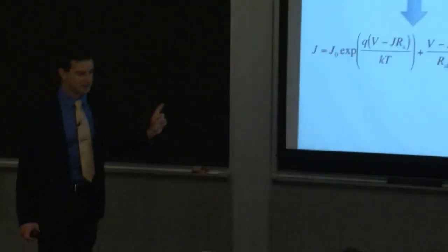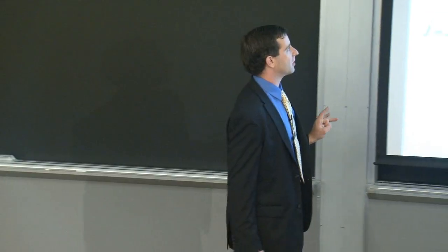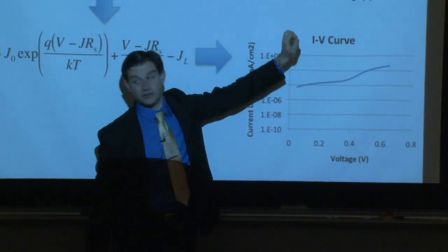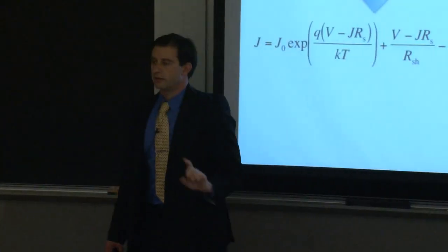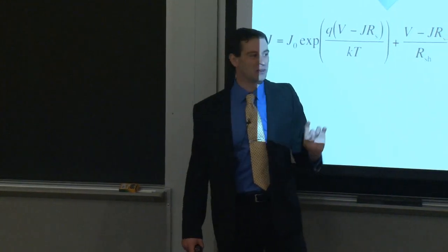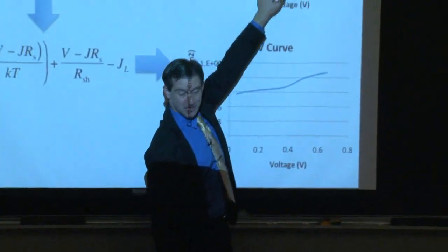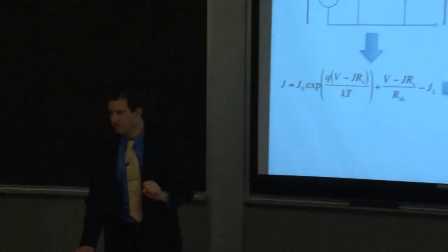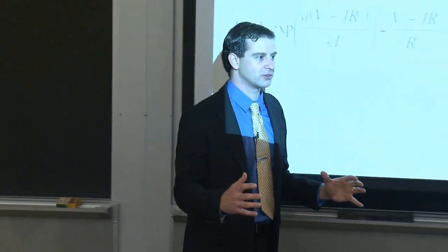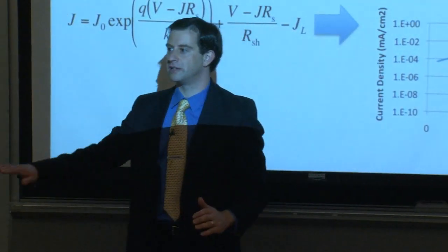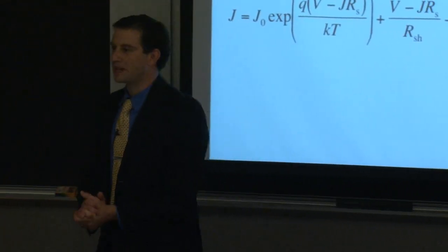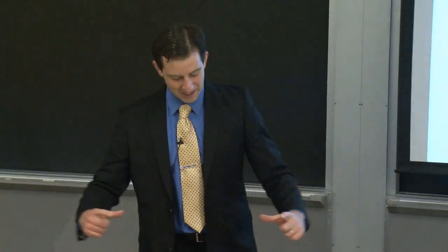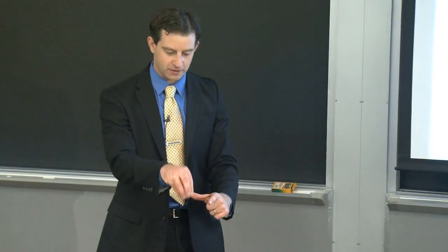So shunt resistance is important for a solar cell device, that it not be too high. Sorry, the shunt resistance not be too low. Yes, your shunt resistance can't be too low because at some point it will begin impacting your fill factor. But more importantly, shunt resistance is usually indicative of some localized failure in your p-n junction. It's usually not homogeneously distributed throughout the entire p-n junction. Well, maybe your first solar cell device you ever make might be affected by that. But as you get better and better, you'll start making higher quality junctions. And usually the shunt resistance is indicative of one little spot.